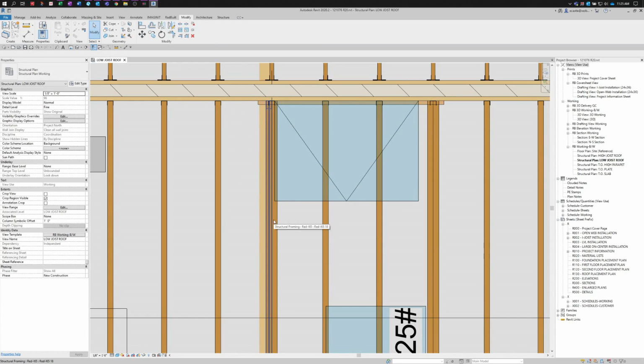Now with the double joists, we have a few options: either a plant assembled double joist, a loose double joist with additional filler and web stiffeners, or just a simple double joist with adding backer blocks for our header.